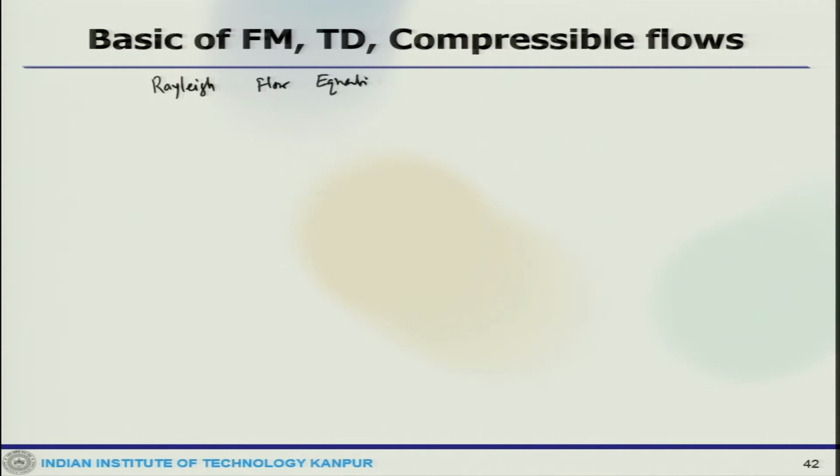This is also a steady 1D flow with heat transfer, so this is important. Thus it is quite appropriate to treat the flow in a combustion chamber as a Rayleigh flow case, because the heat transfer takes place there.